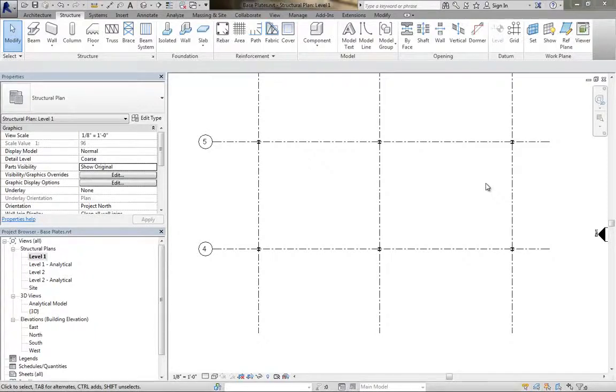Okay, it was asked whether we could have the column base plates be associated with the bottom of the column versus a work plane in Revit. It largely depends on the column base plate family, but as long as that column base plate family can be face hosted, yes, you can have that association in Revit.